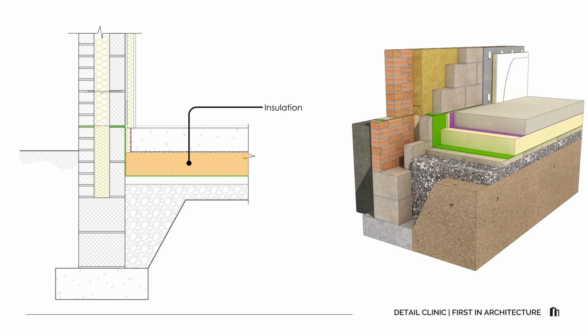The rigid insulation below the slab is continuous and tight to the edges. A separating layer or slip layer helps control the moisture movement within the floor build-up and allows differential movement without scuffing the insulation. The in-situ concrete slab provides a strong, level base to build non-load-bearing walls and floors off.